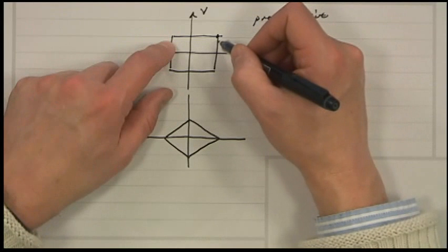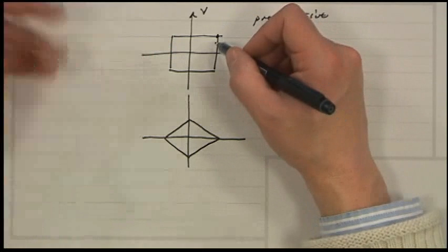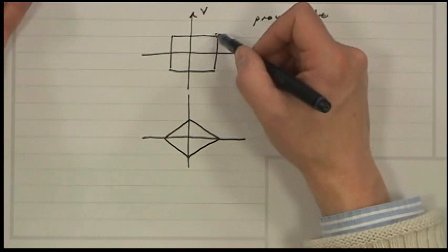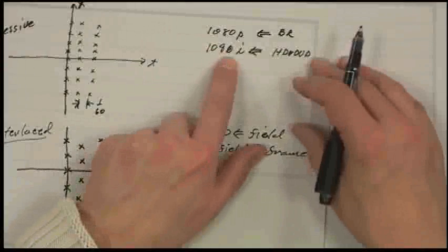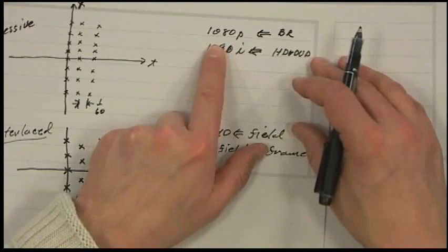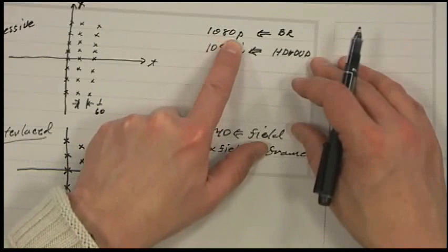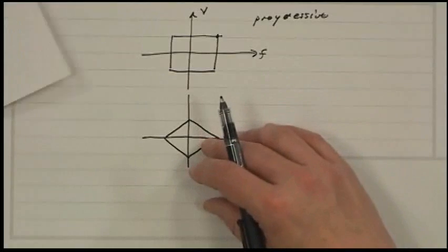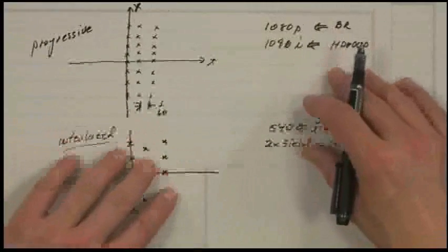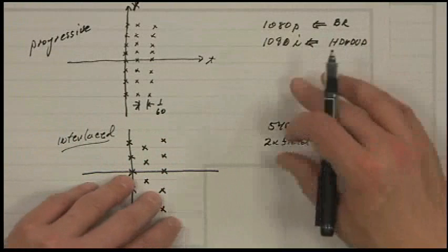Things that move fast and change rapidly and have high spatial frequencies in them, you're visually not sensitive to that, so you don't care so much. So you could have made this number bigger and used interlace and had a lower data rate, at the same data rate produced maybe a higher quality image, because this could be a more efficient format. But the other problem with interlace format is it's just sort of complicated to deal with.